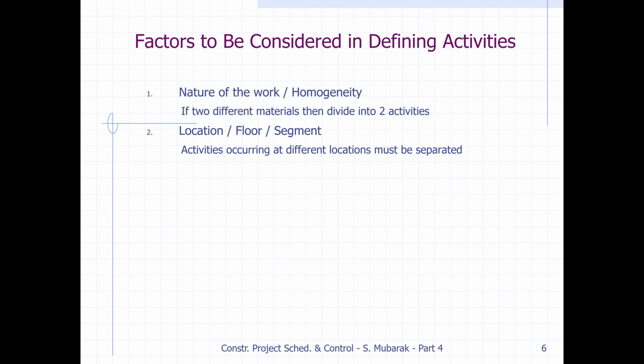So we will assign separate activities, like brickwork on the first floor or brickwork on the second floor. So we should name them differently. Whatever the sections or segments, wherever the location, we should have each activity separate with respect to their different locations. Then size and duration.